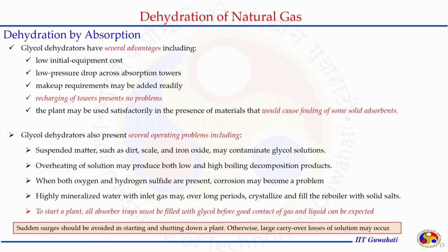More care needs to be taken in terms of putting in the glycol filter, since the pump may get damaged because of the impurities present. In the flash separator, only the gas goes to the vent and rich glycol goes through the reboiler heat exchanger, then the reboiler step. So, at every place, if impurities are present, the efficiency may go down, and we have to be more careful in taking action to separate out these impurities.